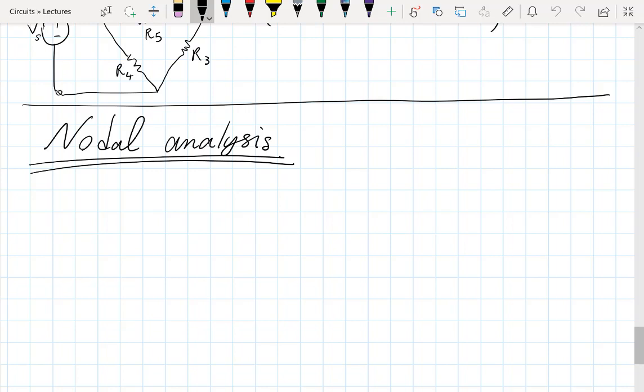Nothing new there, right? I want to combine these equations and eliminate variables to eventually find one of the variables and then work backward and find everything else. If I rearrange the equations such that I first eliminate all the currents and find all the voltages first, and then using those I find the currents, that's essentially nodal analysis, with a caveat, and we'll talk about that.